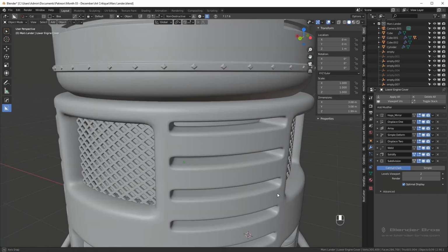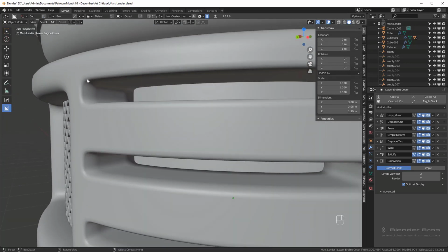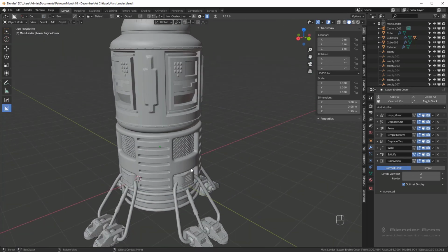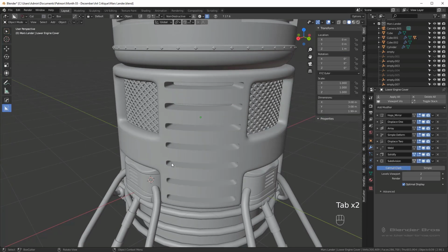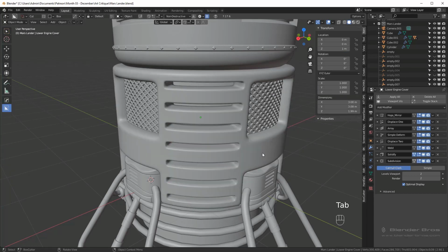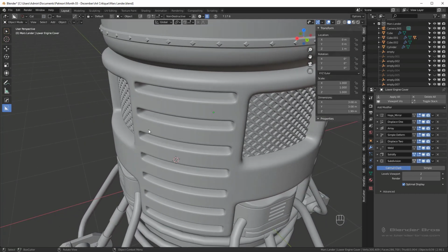So that's probably my only complaint really, because now you can see around these edges here, we have nice reflections and lighting bouncing off of them, right? Look at the difference here. If we, well, I guess it was mirrored around the whole thing. But if I were to bring this back up to 1, now we have no reflection. It just looks kind of blank. And if we bring this back to 0.5 or so, now we have nice reflections around the edges, which is exactly what we want. So that's what I would definitely recommend doing. It might be a bit nitpicky, but I think bevels and edges that aren't perfectly sharp are essential for any sort of hard surface, so keep that in mind.